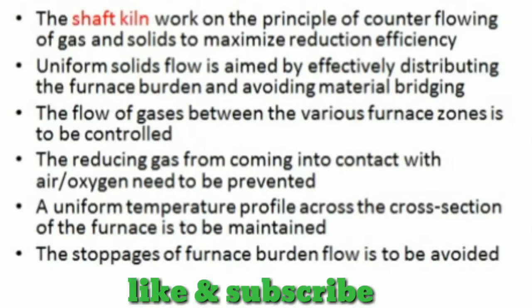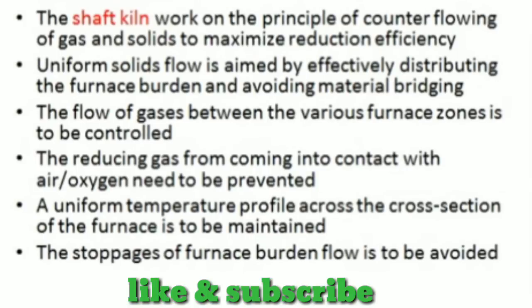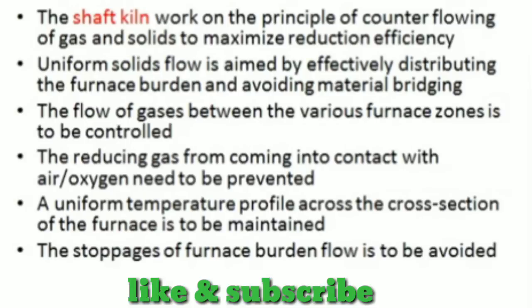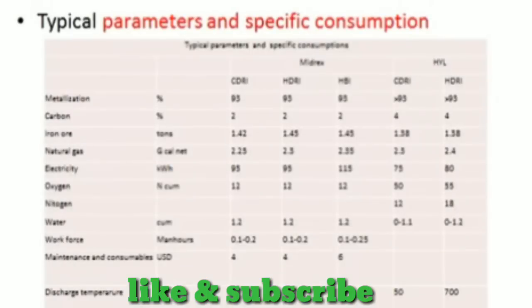The reducing gas must be prevented from coming into contact with air oxygen, otherwise the gas will be oxidized. Uniform temperature across the cross section of the furnace is to be maintained, and the stoppage of the furnace burden flow is to be avoided. That means the furnace burden flow should be continuous and it should not be stopped during the process.